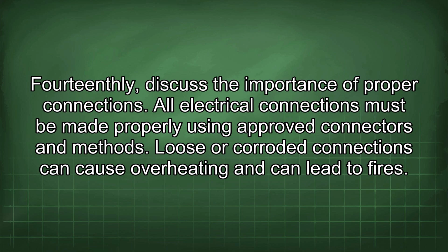All electrical connections must be made properly using approved connectors and methods. Loose or corroded connections can cause overheating and can lead to fires.